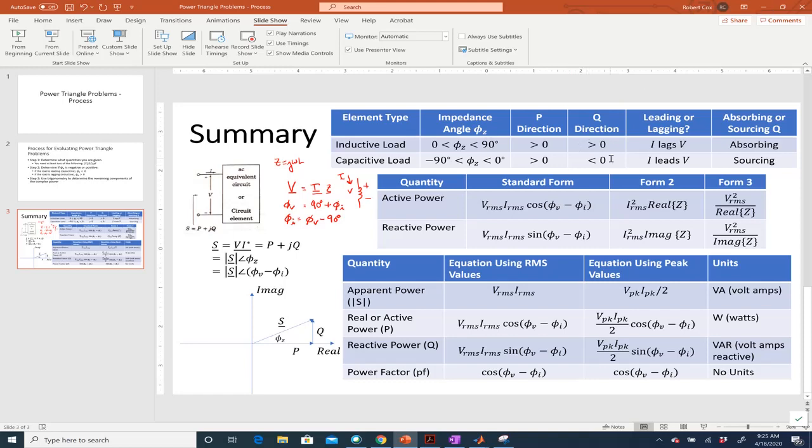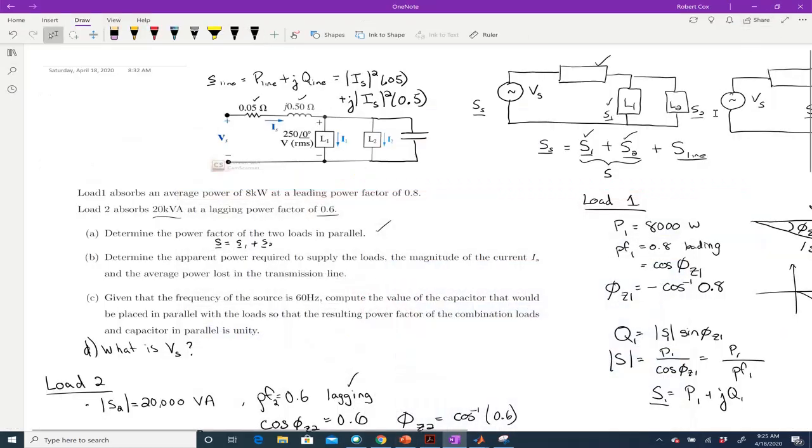And if I have a pure capacitor, there's no P, it's all Q, right? So in this case, I would say that the complex power of the capacitor here is negative, I'm going to write it this way, negative magnitude QC, or just jQC, where I know that QC is a negative value, okay?